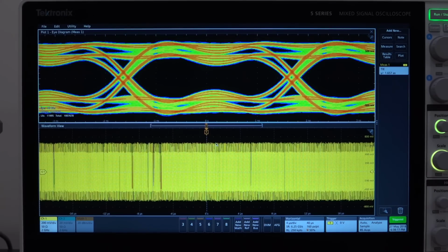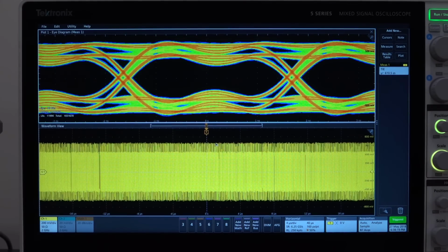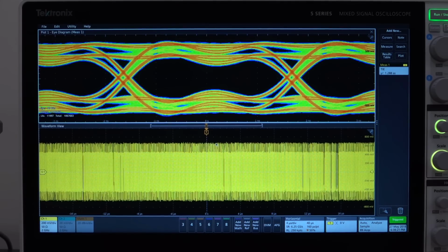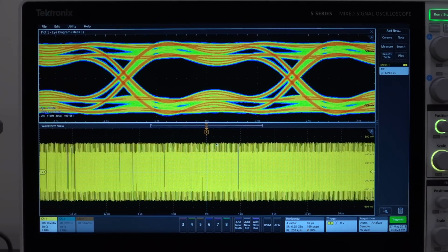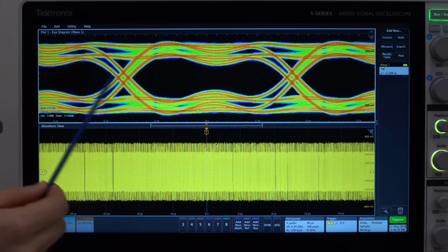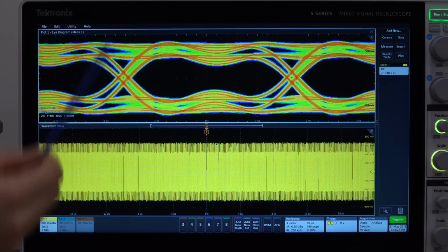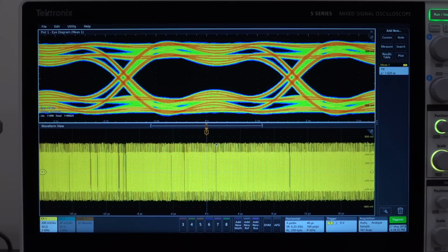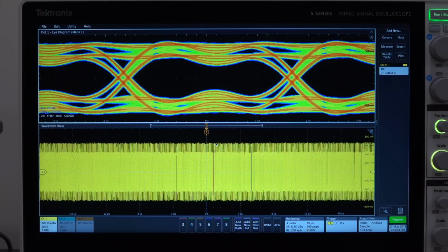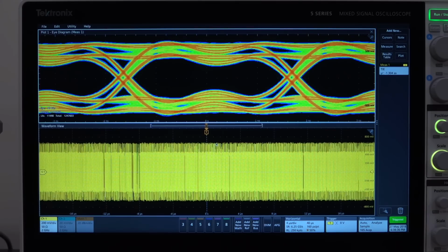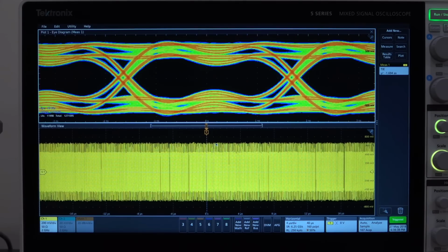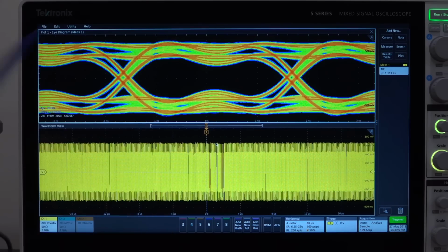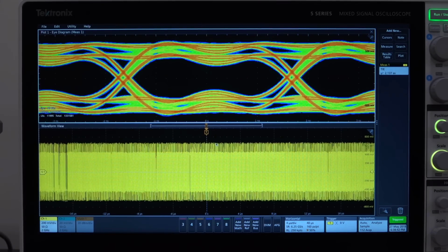And here's another example of what you can do to the eye diagram by combining two channels. And I'm not going to tell you what waveform I'm using. I'm going to let you guess that. But here I'm emulating the effect of having double edging both in the horizontal and in the vertical side of this eye. And this can be useful to emulate the effect of some extreme ISI cases and extreme vertical noise there, which is kind of well defined. And this can challenge some CDRs to fall into some conditions which they're not supposed to.